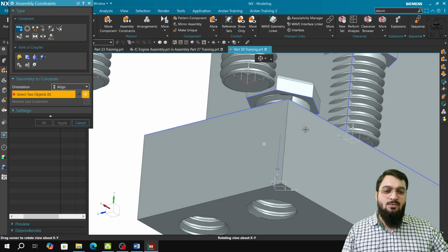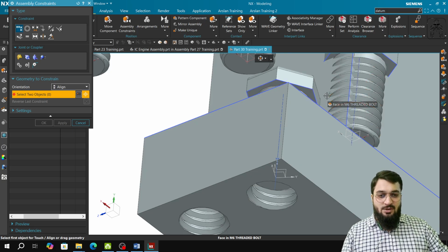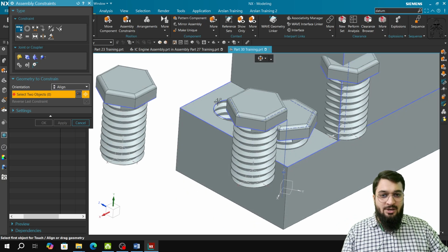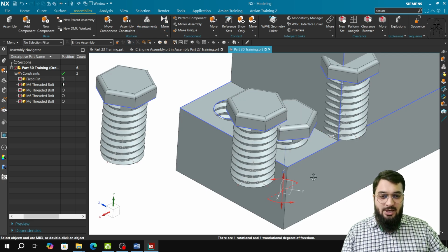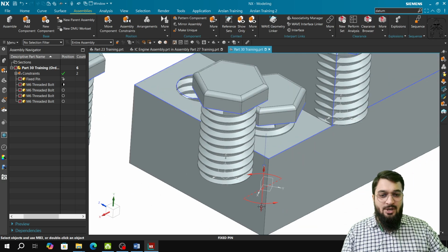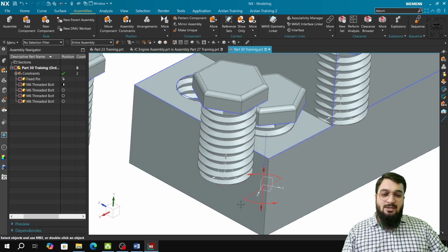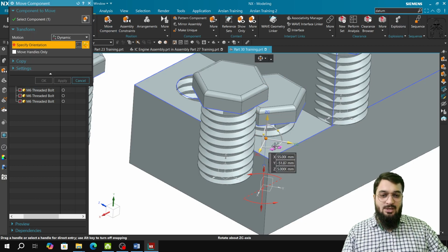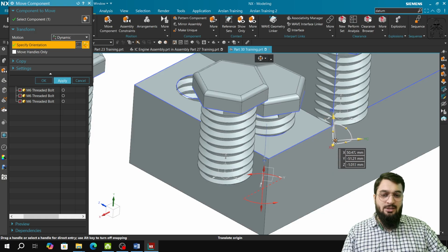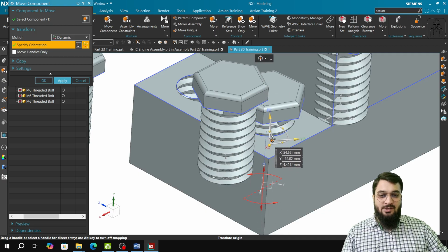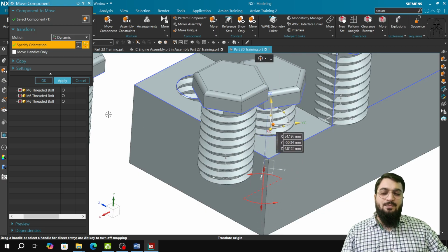After that, if I want to touch this particular surface and I do not want this linear translation motion to happen, I'll show you the degrees of freedom this particular thing has, and you will see that it has the degree of freedom in the y-axis and the rotation about the y-axis. I will also show you by moving that orientation. It can rotate in this manner, it will not rotate in this manner, and it will not translate in either this axis or this axis, z or x axis. It will only translate in the y axis.